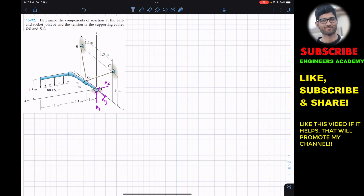Here, for this 3-meter length of this beam or assembly, we have this load distribution. This is 800 Newton per meter, so the load is distributed over this 3 meters length. The resultant of this distributed load will be 800 multiplied by 3, which is the area of this distributed load.